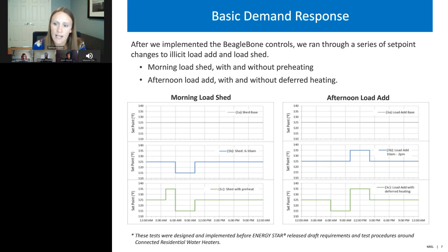So for each scenario, we had a base case where the set point was static, so set at 125 the full day. And then I'll start with load shed, a basic load shed test where we had 4 hours where the set point was reduced by 10 degrees F. And then an advanced case where we had a preheating followed by the load shed.